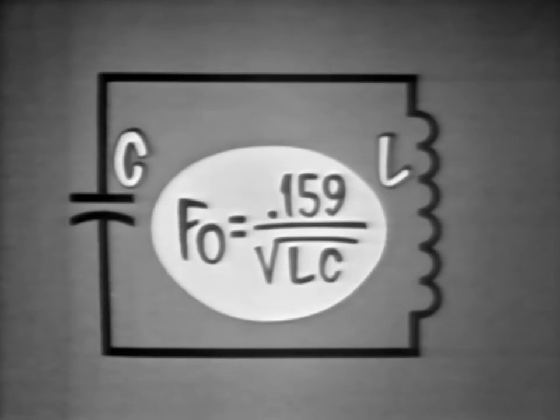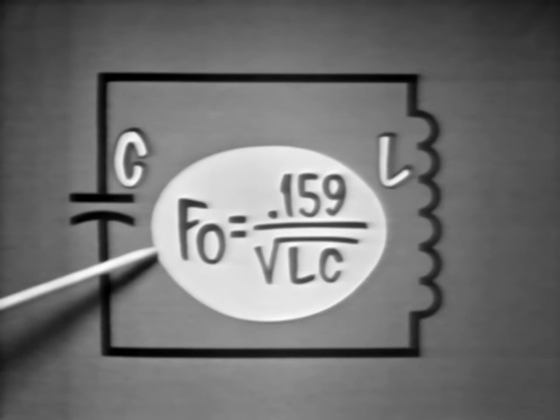We have seen that an amplifier will oscillate without a frequency-determining device. But the frequency is determined by distributed L and C, which makes frequency difficult to calculate and erratic. This kind of oscillation is usually undesirable. A frequency-determining device, in this case the LC tank, provides a stable, easily calculated frequency.